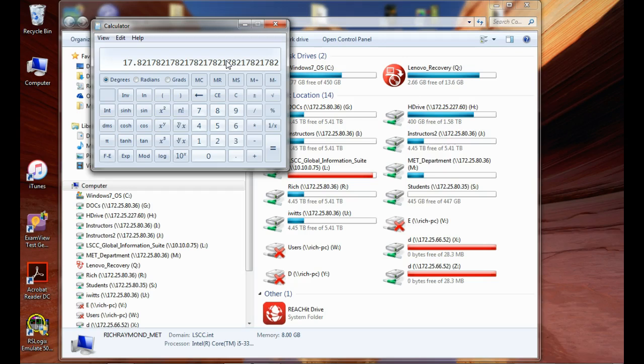Now, of course, if I don't filter it, then we wouldn't have enough voltage, right? And my regulator wouldn't work. So, okay, I got 17.8 volts, which is what my capacitor is going to charge up to. Of course, if I'm going to use a full wave bridge, then I would come up here and I would subtract what? I would subtract 1.4 volts. So that's what we have to work with, 16, which looks like it's pretty good for a 12 volt supply, right? That's only 12 volts between what I need to do.